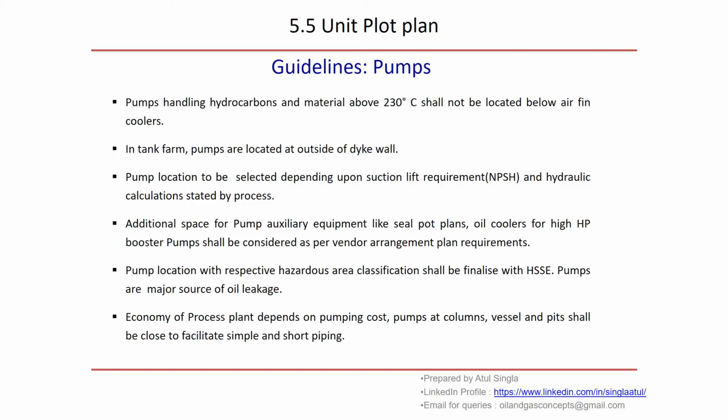If we are preparing a plot plan for a tank farm, then pumps are located outside the dike wall. This is fixed everywhere: wherever we have a dike, we have pumps outside the dike. Pump location is to be selected depending upon the suction lift, NPSH and hydraulic calculations stated by process. All these calculations are done by process only, and this information is given to the piping team through P&IDs. Based on that, we locate these pumps. That means the NPSH and hydraulic calculations are very much required to finalize the location of the pump.